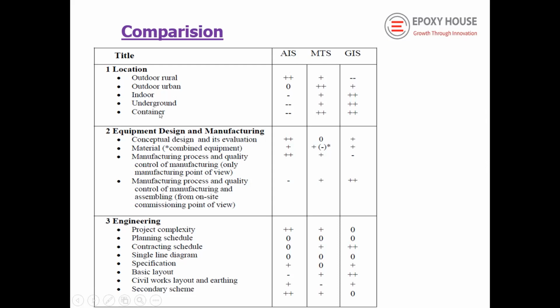Then the container substation can be made; there are prefabricated substations available. IEC has also formed standards for the prefabricated gas switchgear requirements. So for that also, GIS is critical. What is interesting with the container substation is that you may have to carry it to a substation that is already functioning, and transfer the power through this switchgear.